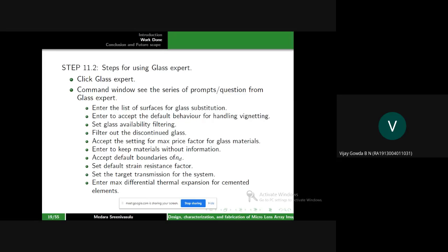And in this design, I'm going to use 2 achromatic doublets, on the front side and the back side also. And then differential thermal expansion matters, because there is no air gap between them. When you keep it in different types of environments, that means cold environments or maybe hot environments, that gap is going to be created or maybe reduced. That will also cause a depletion in the performance of the system.